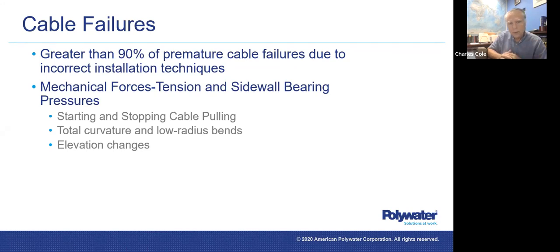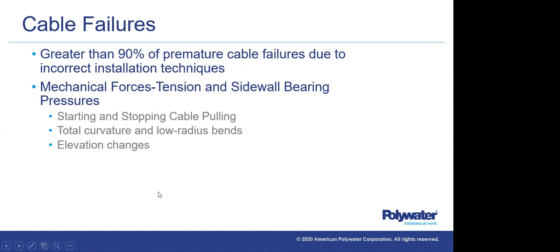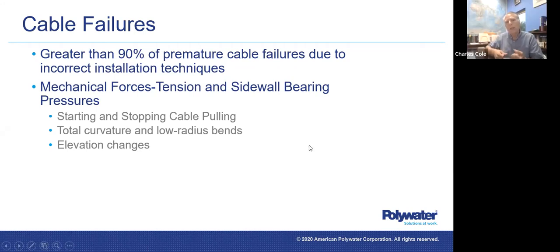Mechanical forces could also be very, very high due to starting and stopping cable pulling. I've seen that a lot in India, and we want to avoid that, because once the cable has been stopped, to get that cable moving again you have to exert a lot of force on it, and that can damage the cable.